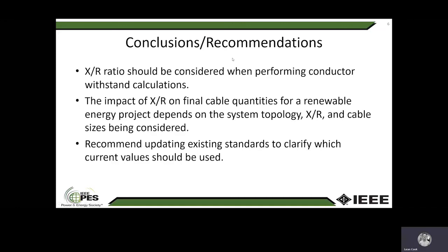So in terms of final conclusions here, my claim is that the X over R should be considered when performing these withstand calculations, and that it is important to keep in mind the actual impact of the X over R on these cable quantities depends on a lot of things, including the system topology, the actual X over R, the X over R of the main power transformer, and the cable sizes.